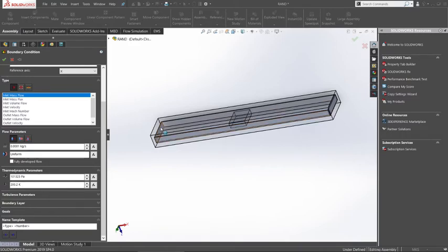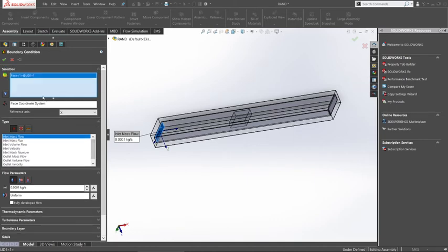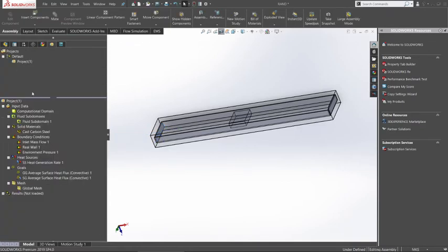and then you apply the surface, because you have to select which surface is your inlet mass flow, with the values of the inlet mass flow and their thermodynamic parameters, and there you go, you have your boundary conditions. Similarly, I've done inlet mass flow here.